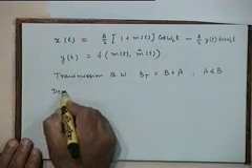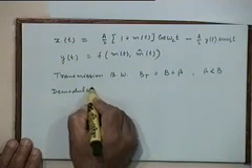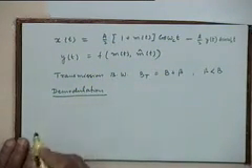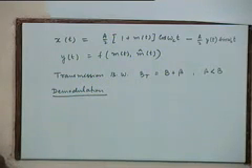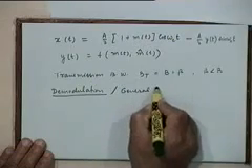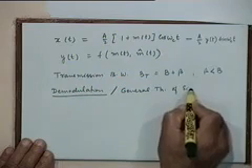Now demodulation is what we would like to spend some time on, because that leads to some crucial questions and answers. In the process, we will also look at a general theory of sideband filtering, which will include SSB as a special case. So VSB is a general case and SSB becomes a special case in which beta is equal to 0. So we will in the process also discuss a general theory of sideband filtering.